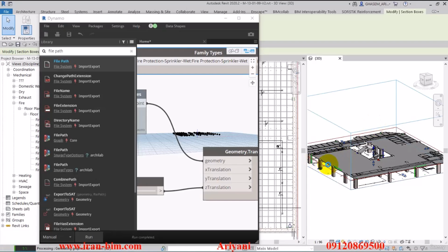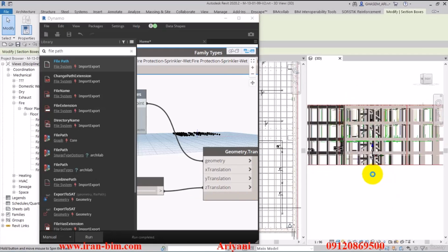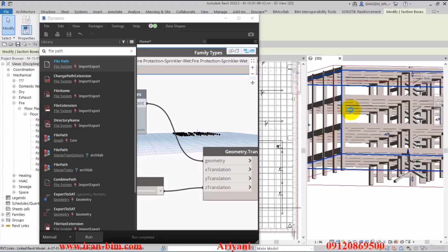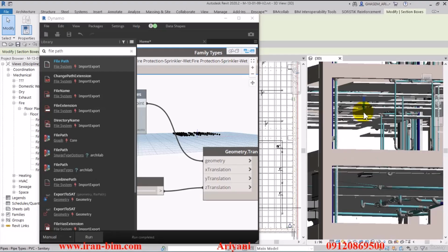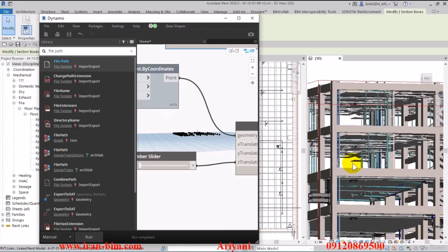Because the coding for this is minus, we need to put in minus for the height in the Dynamo as well. Right now it's located at plus 2.1. We'll just have to wait for this to load up and see what we have here. Alright, now let's rotate this and then we can zoom out to see this part in full detail. And let's also put the Dynamo on manual settings.